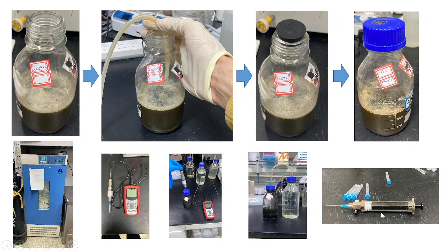Afterward, you can use gas sampling injections. This one was slightly expensive, purchased from Agilent, because it does not allow oxygen to get inside it, and it is very precise. So you can take samples from this headspace and insert this sample into a GC or methane meters, simple methane meters, and insert all these parameters in the ideal gas equation and measure your methane produced from a specific feedstock. After that, as I mentioned, you can record your daily methane yields, and if you want cumulative methane yield, you can sum up all your daily methane yields and prepare a graph like that. I will cover all those details in next videos.